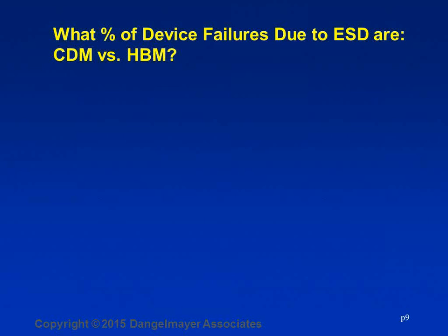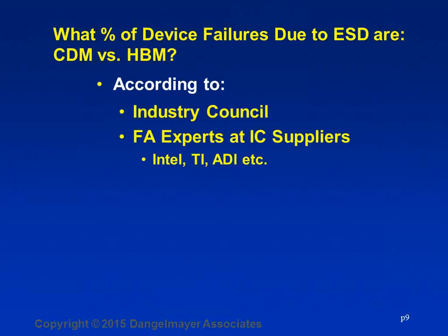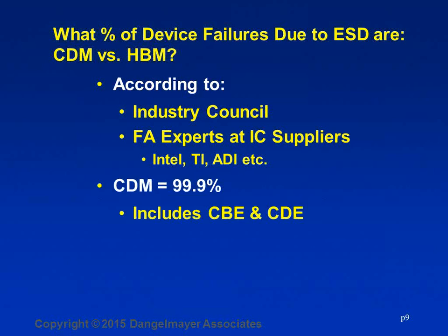Now, what would you estimate the failure rates to be in comparison? This is across the industry, and it's based on input from many credible sources, such as the Industry Council and failure analysis experts from IC suppliers. So what would you think is the relative occurrence of failures between CDM and HBM? Well, it turns out that CDM dominates the failure mechanism and has for some time.